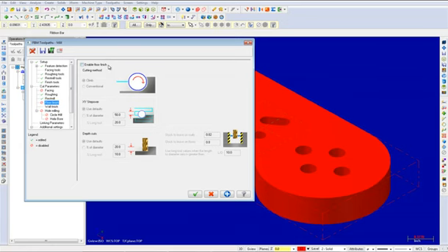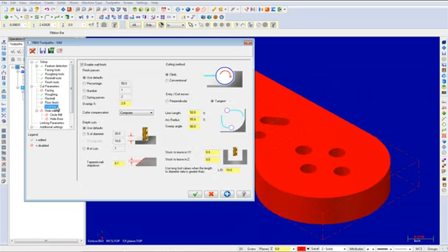Next, select wall finish. With this option enabled, Mastercam will add finish passes for the walls of each pocket feature included in the FBM Mill operation. When this operation is deselected, Mastercam creates only roughing and rest mill operations for pocket walls. Make sure this option is enabled and set the finish passes to number with a value of 1. Also, set the depth cuts to number of cuts and input a value of 1. Finally, change the LD value to 3.